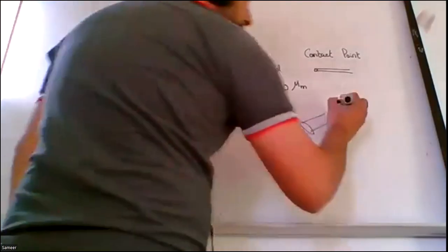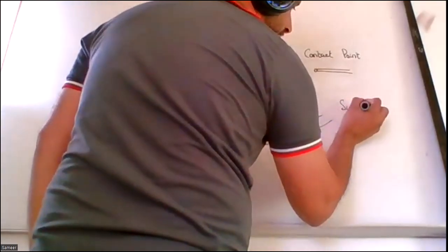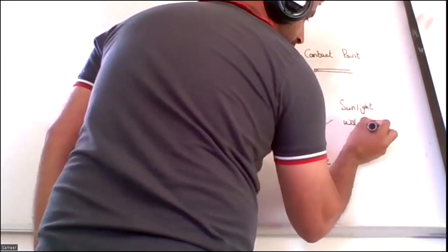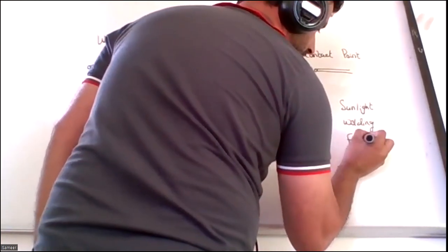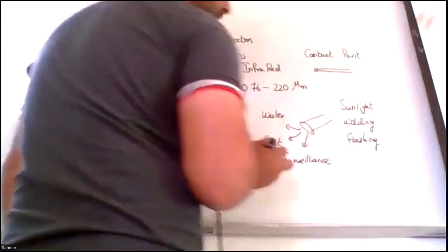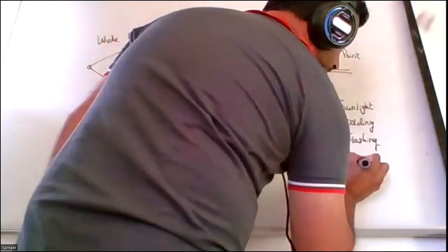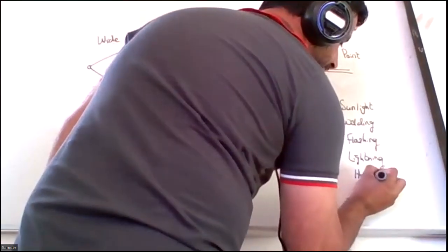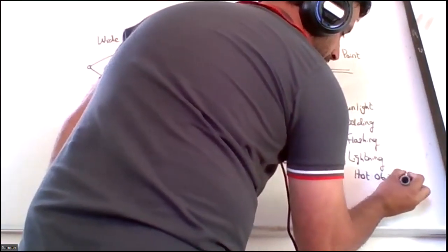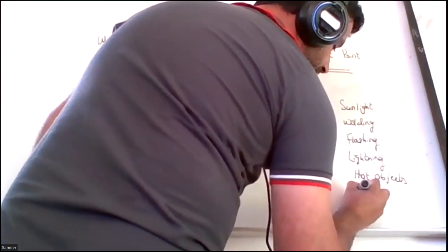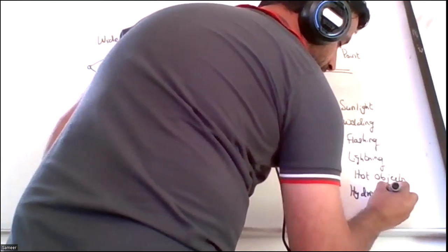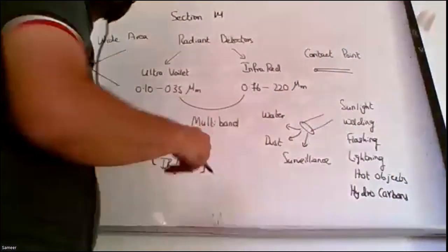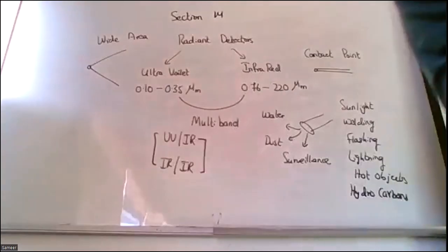Then sunlight, welding, any flashing of lights, lightning, hot objects, hydrocarbons: a lot of reasons can trigger the ultraviolet and infrared detectors.